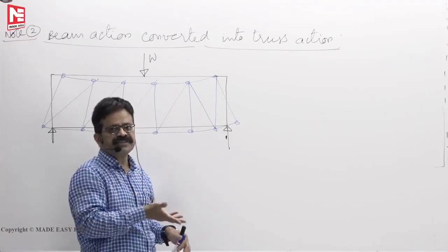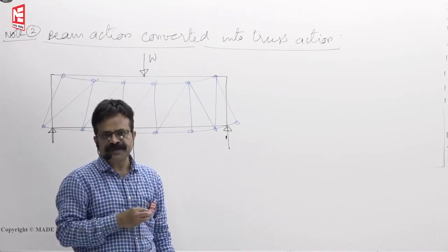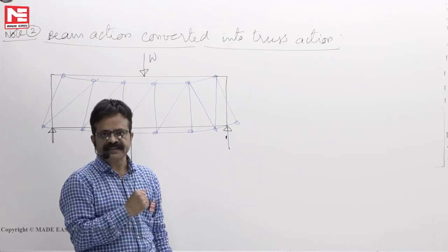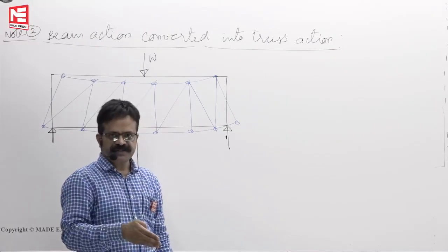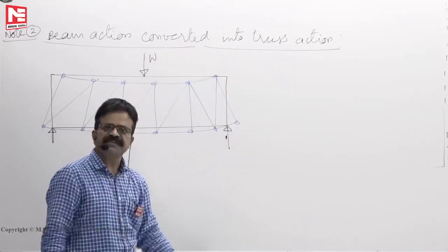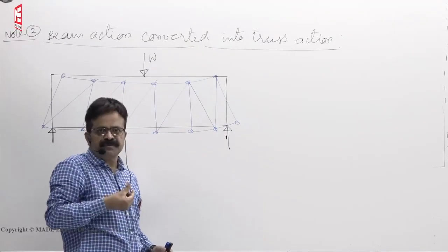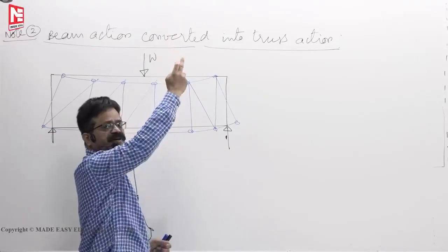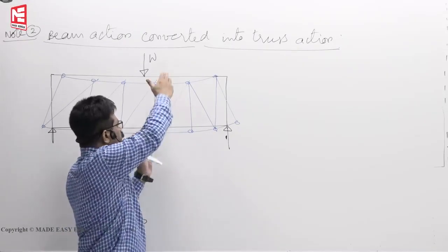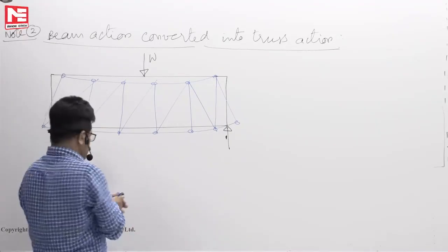Waste of money, shear force and shear stresses. If you see strength of materials notebook, the shear stress value is around 15 Newton per mm square, like that will be there. But its capacity is 250 by root 3, like that. So much underutilized cross section. So where you have a single wire or single rod can resist the shear, why should we have entire rectangular cross section and waste our money? So panel shear is resisted by the diagonal members. Length may be say 4 meters or 5 meters, whose cross section will be very small compared to the length. So axial force will be there, whose y component will resist the panel shear. So this is what happened.